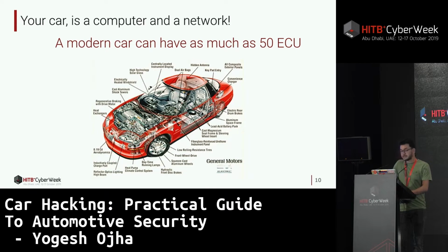Things like predicting the crash, detecting slides, anti-lock braking systems, and so on. Now, with all these things, they need to be networked, right? So these days, it is pretty much done using something called CAN, generally called Controller Area Network. All of these ECU components talk to each other by sending CAN packets.